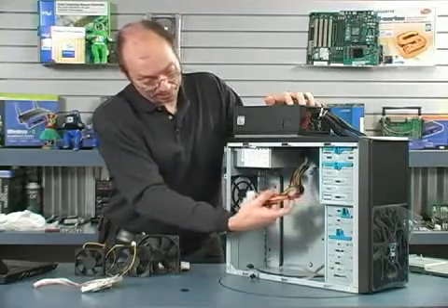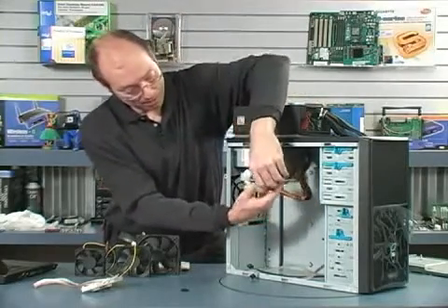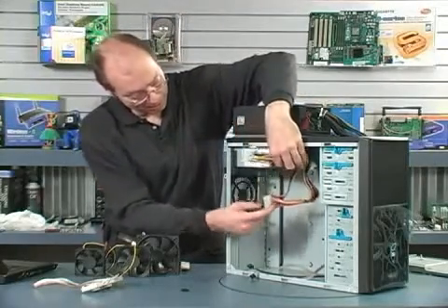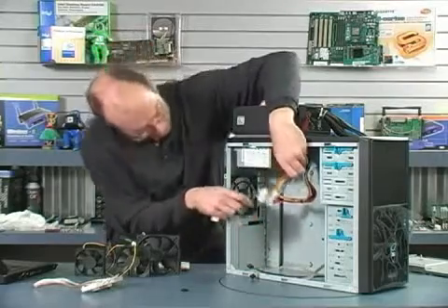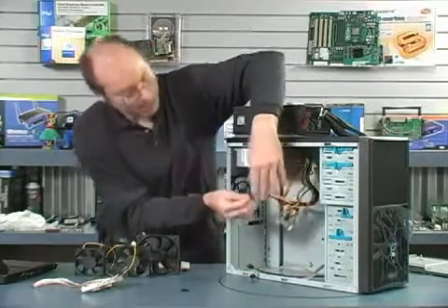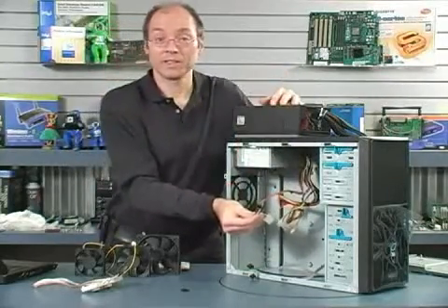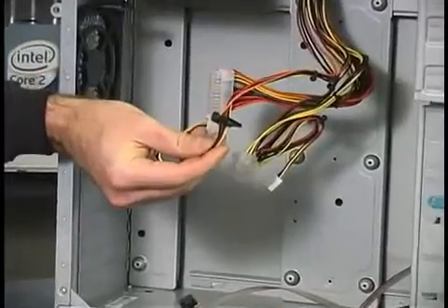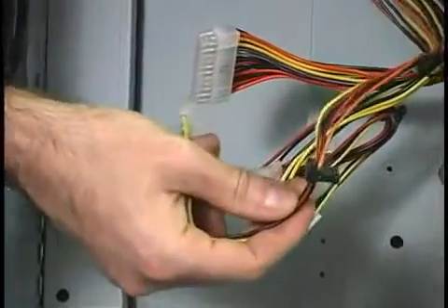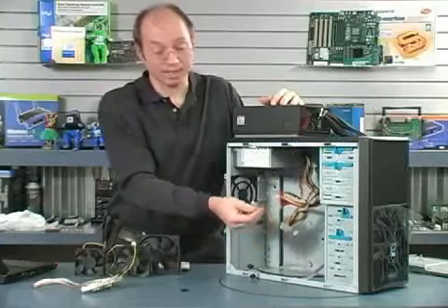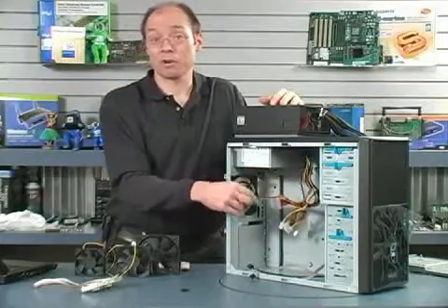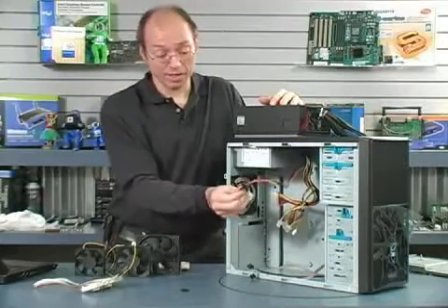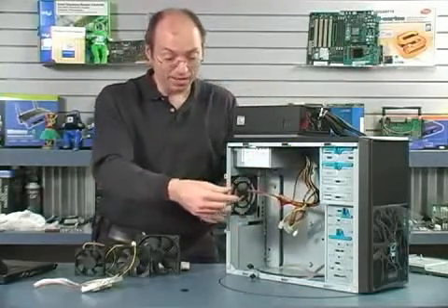For example, I'll note a couple problems with this one. This power supply that came with this case has literally one SATA serial ATA drive power connector. Now I plan on installing 4 hard drives in this case, and I could fit 6. I'm not going to be able to power 4 or 6 hard drives with a single connector like this. Now you can get adapters.